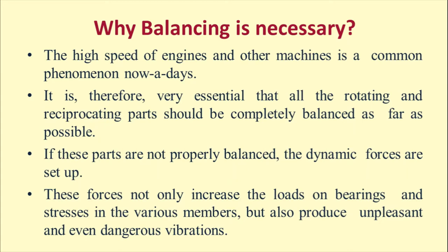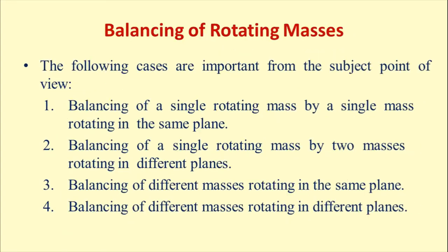Now if these parts are not properly balanced, then dynamic forces are set up. These forces not only increase the load on bearings and stresses on the various members, but also produce unpleasant and even dangerous noise and vibrations. The following cases are important from the subject point of view: balancing of a single rotating mass by a single mass rotating in the same plane, balancing of a single rotating mass by two masses rotating in different planes, balancing of different masses rotating in the same plane, and balancing of different masses rotating in different planes.